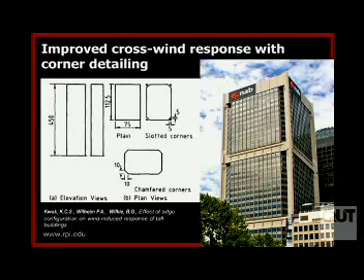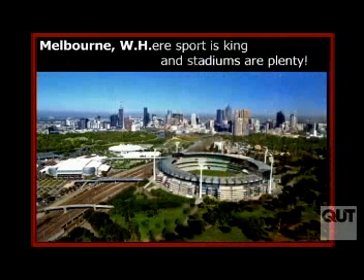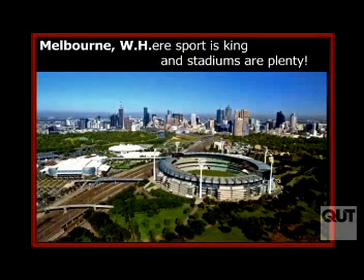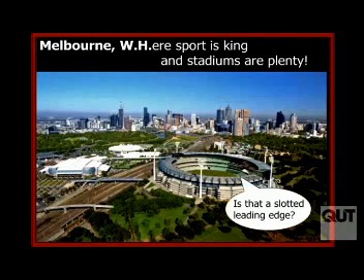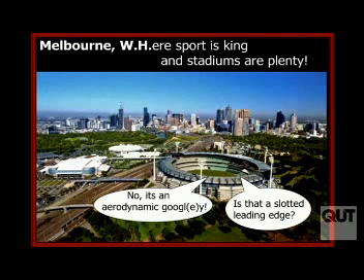Those of you familiar with Melbourne, the NAB building, Bill Melbourne did this tunnel test, and again, slotted corners on this building improve the aerodynamic performance of the structure. And of course, this application Bill took to a whole new extent with sports stadia, where he introduced the slotted edge of the sports stadia to again do this same thing of interfering with the flow as it separates, so to try and make sure that any sort of wake excitation is eliminated. So again, it's a way of fooling the flow so that it doesn't cause this resonant type condition to occur.